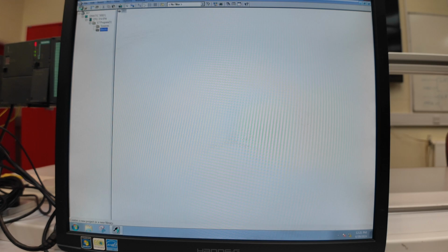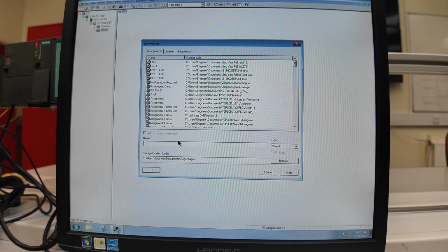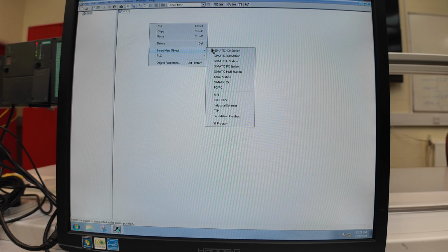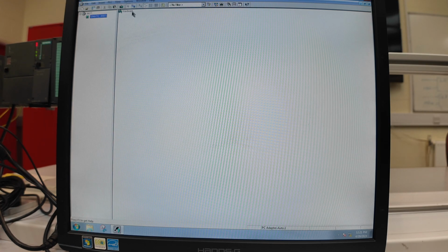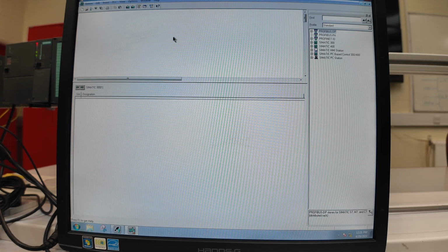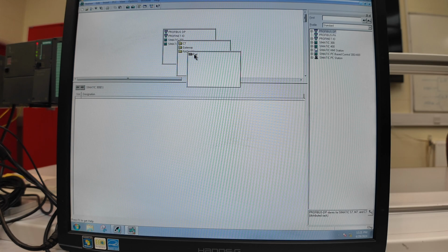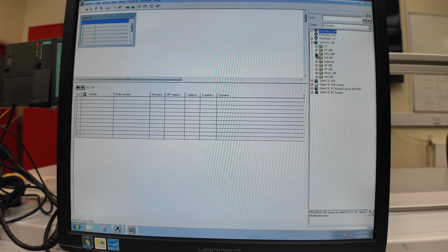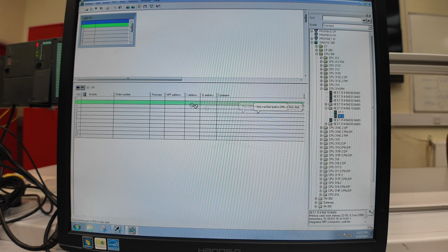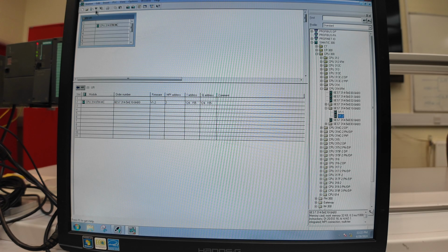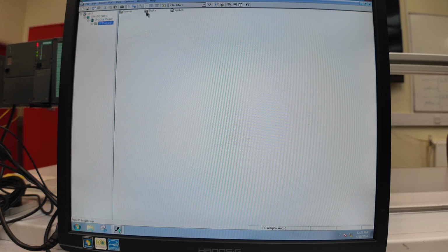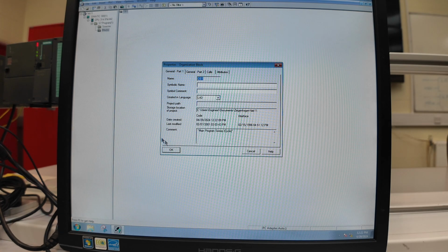So this is then the first lab about the timer and counter. We start by creating the project. Then we insert our PLC station, do the hardware configurations, insert our rack. Then we place our CPU for the simulations. Then we go on our program, open the OB1.